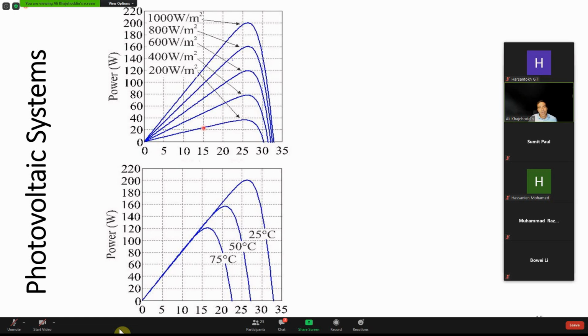So depending on how good you can adjust this output voltage, the power you're going to get from this PV panel is going to be different. This is changing all the time, and it's a nonlinear characteristic, because as soon as you have cloud, you are operating here, all of a sudden you're operating here, right? Because the characteristic of a PV is changing.